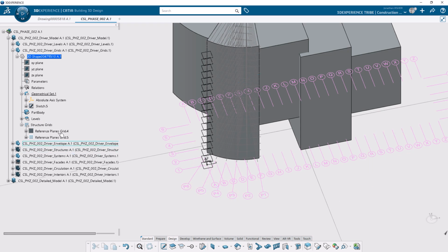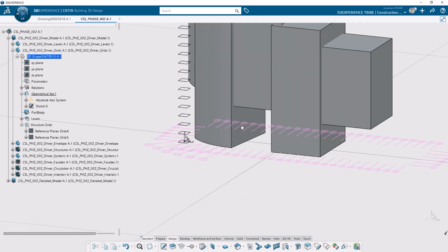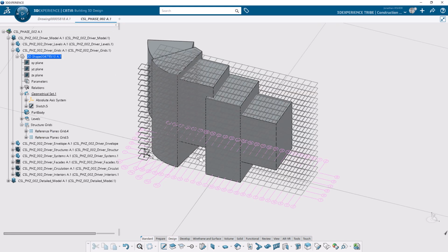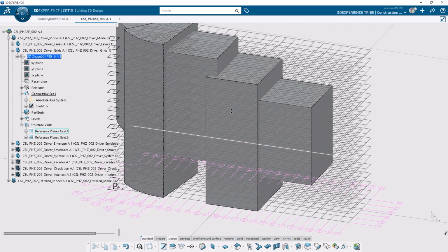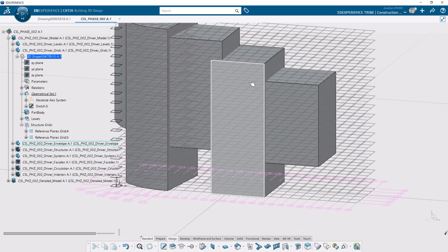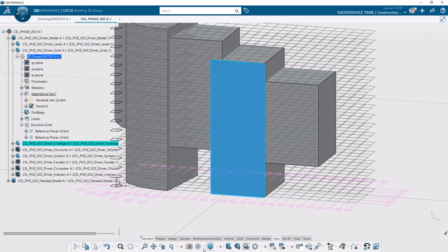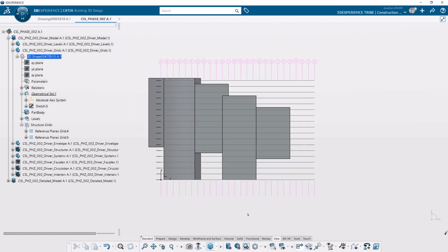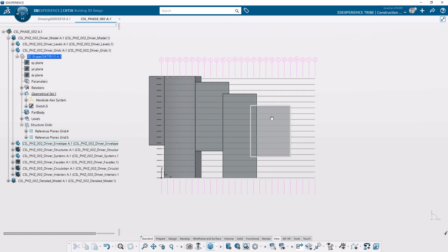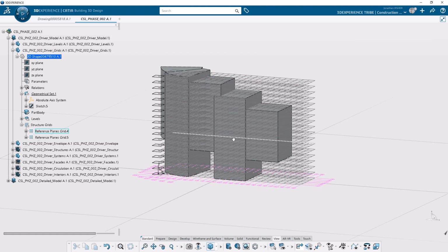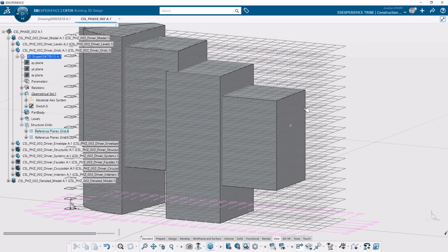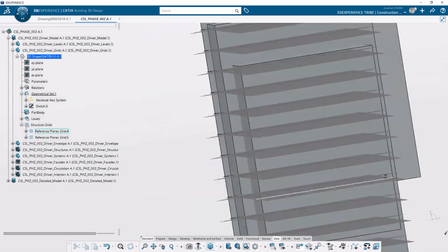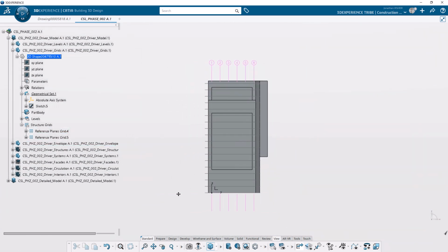But there's another nice thing about the way the grids are visualized depending on your orientation. So if you select a face and go normal to that face, where you position yourself perpendicular to the grid, you see that the grid visibility will then flip to be parallel to the view or perpendicular to the view, depending on your perspective or orientation. Similarly, for the other side of the grid, going parallel to that view plane is going to give you the visibility of the grid along that view.